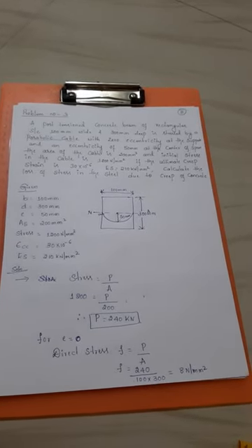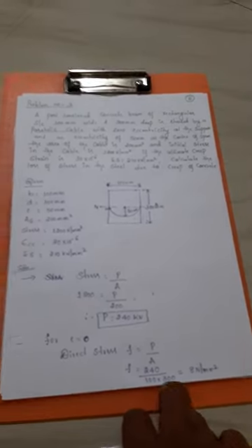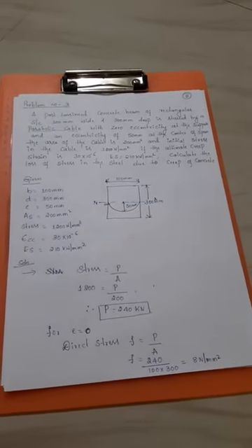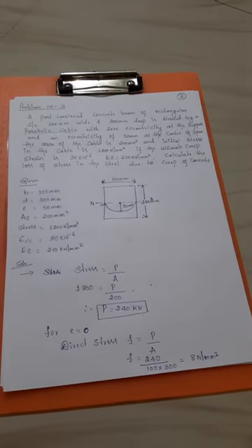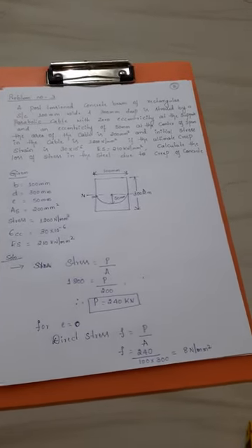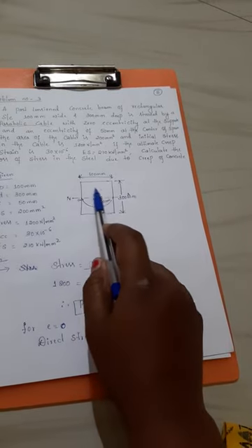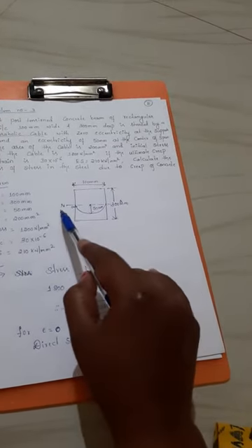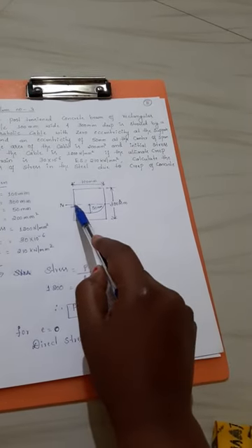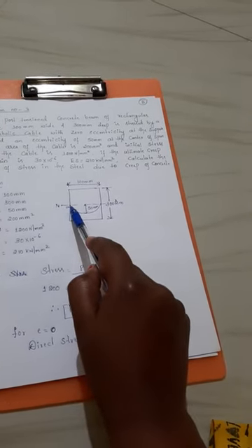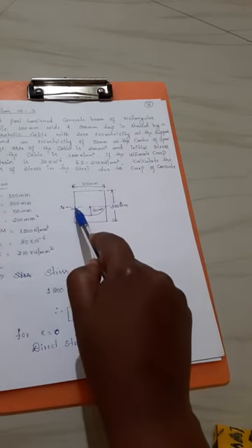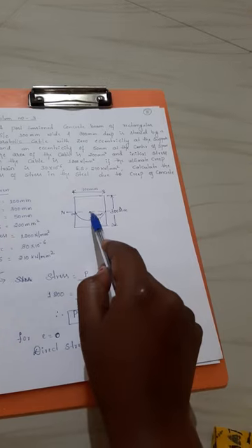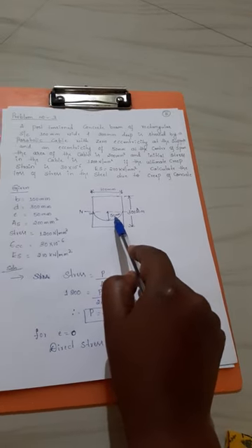Okay, ultimate strain coefficient method alli calculate ಮಾಡಬೇಕು. So write down all the given data. One is breadth has been given 100 mm and depth also has been given 300 mm, and they have given an eccentric distance also. Look at this diagram. I have taken a rectangular section, so 100 mm wide and 300 mm deep. This is your neutral axis. In the question they have mentioned this is in a parabolic cable with the eccentricity is 0 at the support, and at the middle the eccentric distance is 50 mm. Okay, so I have taken that.